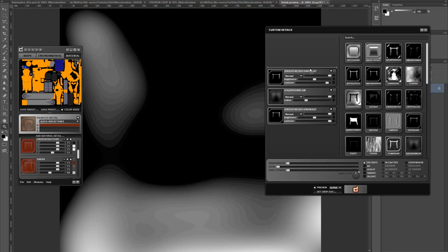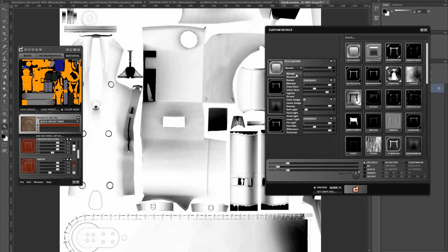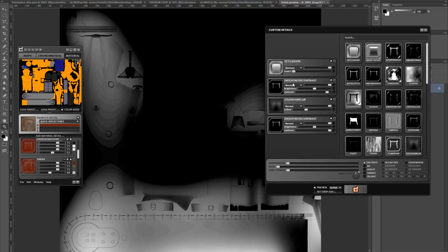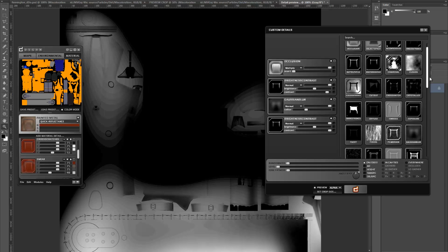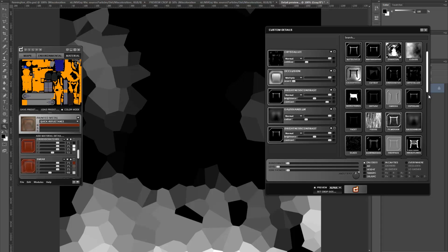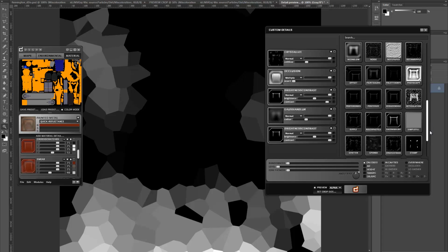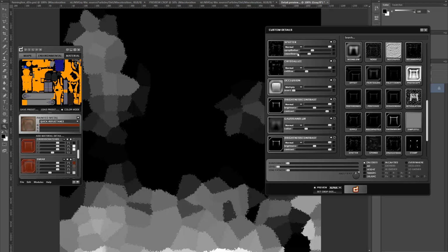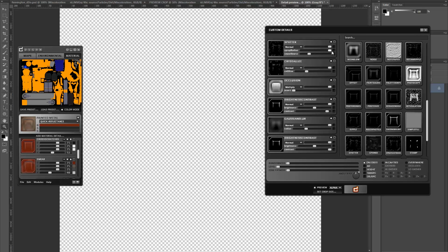And seeing as this is going to be a wear and tear detail, I think it's really important to specify where on the model it's going to be. So I'm using an occlusion node, which allows me to mask out the areas that aren't really sticking out very much. Now I'm adding a crystallized node, which allows me to sort of simulate how peeled or worn paint would look like chips falling off. I'm adding a spatter node to further increase the amount of fidelity in the mask.